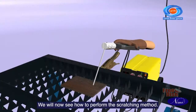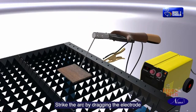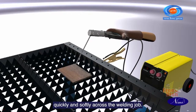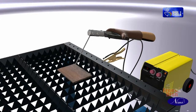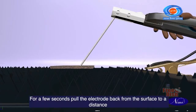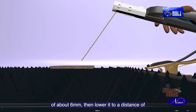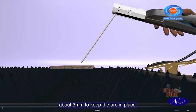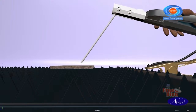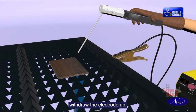We will now see how to perform the scratching method. Strike the arc by dragging the electrode quickly and softly across the welding job using wrist movement only. For a few seconds, pull the electrode back from the surface to a distance of about 6 mm, then lower it to a distance of about 3 mm to keep the arc in place. To break the arc quickly, withdraw the electrode up.